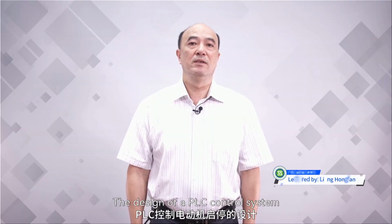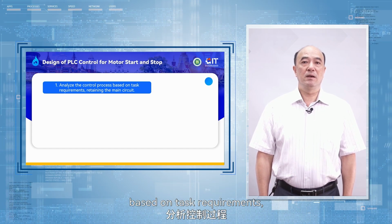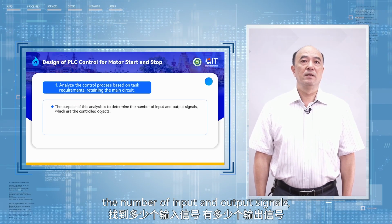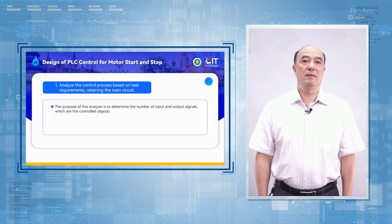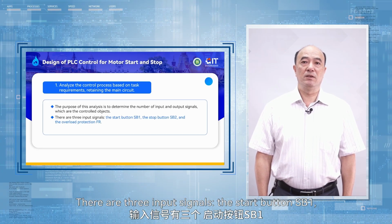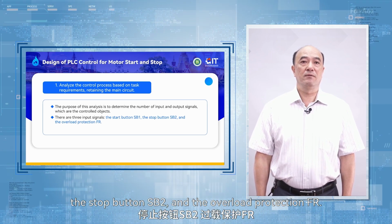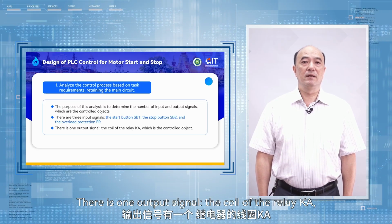The design of a PLC control system for motor start and stop must follow 5 steps. 1. Analyze the control process based on task requirements, retaining the main circuit. The purpose of this analysis is to determine the number of input and output signals, which are the controlled objects. There are 3 input signals: the start button SB1, the stop button SB2, and the overload protection FR. There is 1 output signal, the coil of the relay KA, which is the controlled object.